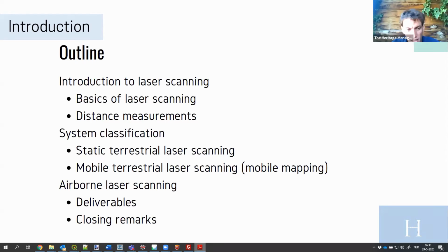Another way of acquiring kinematic data is, of course, airborne laser scan data. I know that especially in the United States and in many European countries, you can have free access to airborne laser scan data. That's the situation where the vendor of the data has put a laser scanner in an airplane. The area has been flown over by the airplane or a helicopter, and you can have laser scan point clouds of your area of interest.